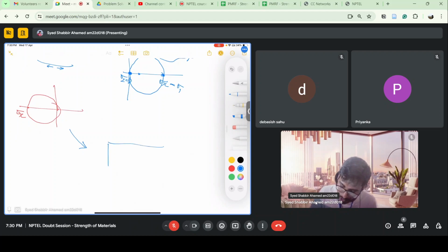So if I have an axial load applied like this, at the point of application of load some irregularities will be there. So we go a little bit far from the application of load. That is called Saint Venant's principle. Everything will get the same color. For axial stress, we'll get same color fringes.